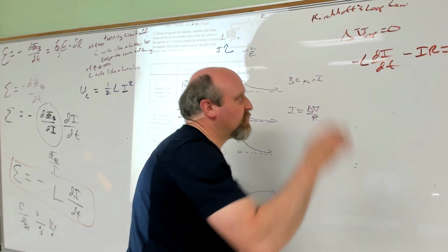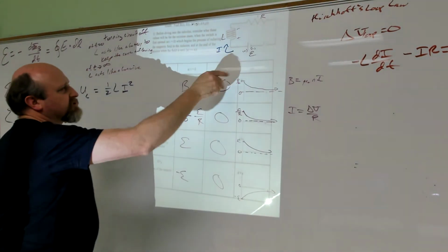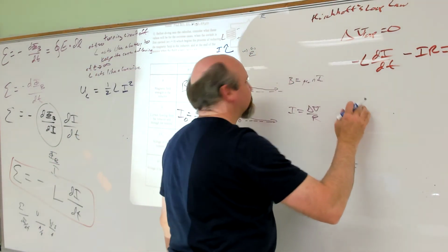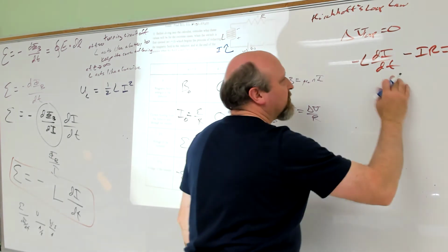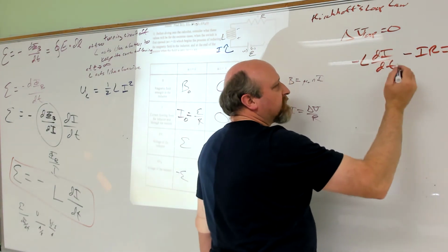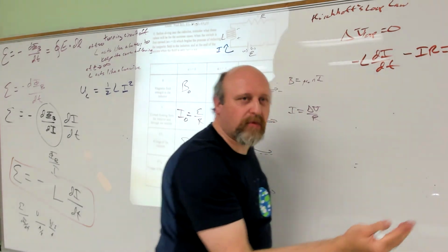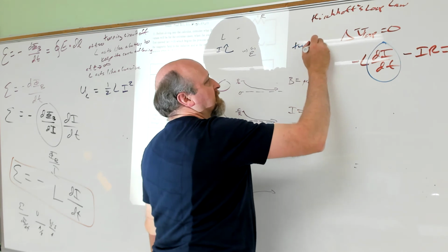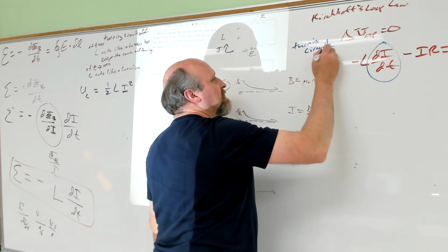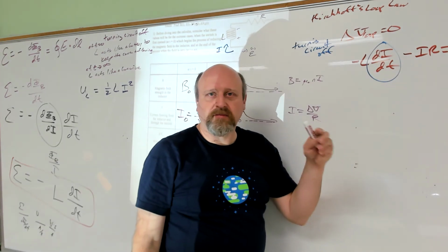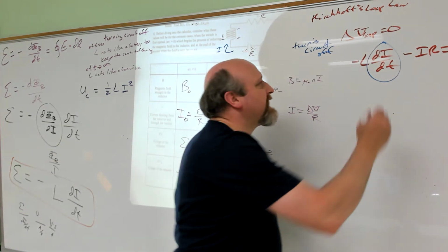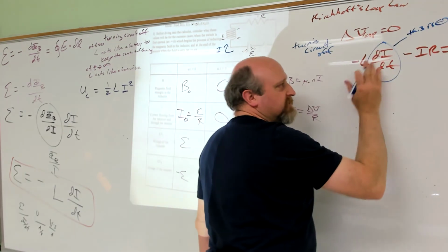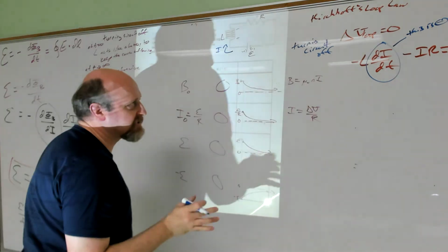This derivation is actually way easier. The one for turning the circuit on is more complicated, and that's the one I wrote out for you. Here the math is really easy; the other one needs a substitution, and it's crazy. But what I want to point out is: wait a minute, negative and negative equals 0, how's that working? This is for turning the circuit off, so what's di/dt, my rate of change of current? My current is decreasing, so it's negative, and that negative makes this term positive. Then positive and negative give me 0. In case you're wondering, that's what's going on there.